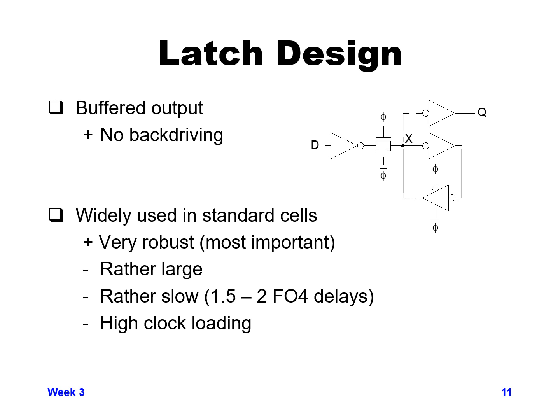The downsides are, since it has more transistors than all of the other ones that we looked at, it's a larger latch than other ones. It's a little bit slower. It has 2 inversions along with the pass gate. Some of the other latch designs we looked at had only a single inverter, so they could be almost twice as fast.